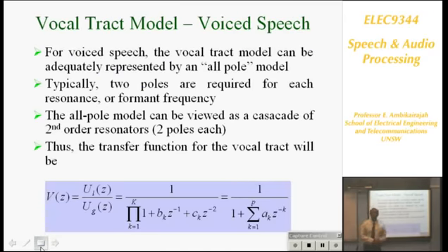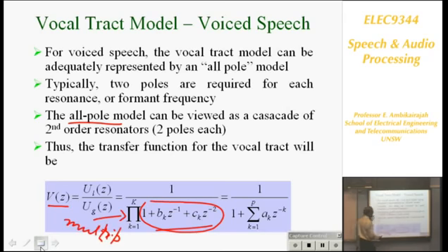Here is my vocal tract now. What is the vocal tract? I have got second-order filters, 3 of them at least, because I want 3 resonances. Normally you get 4, an 8th order filter. We don't know how many orders, so we just say, if you want to go for vocal tract modeling, you go for an all-pole filter. Everything is poles, meaning you only have poles in the denominator. The vocal tract transfer function is one second-order section multiplied by many others, with a multiplication sign, and k has as many as you want.